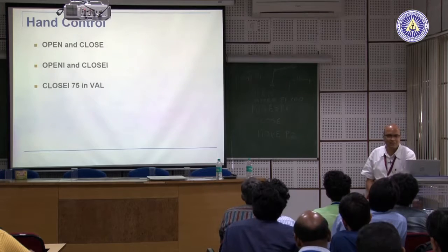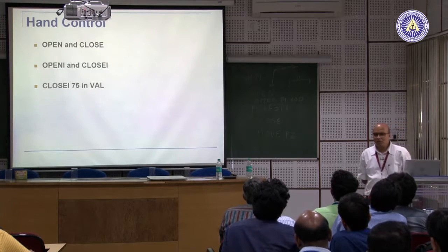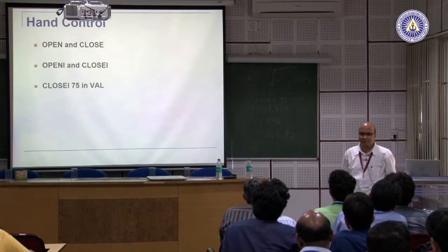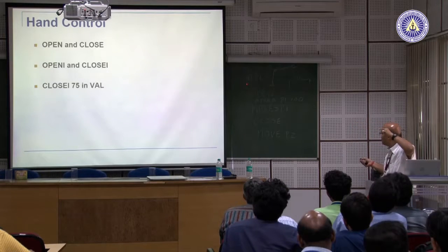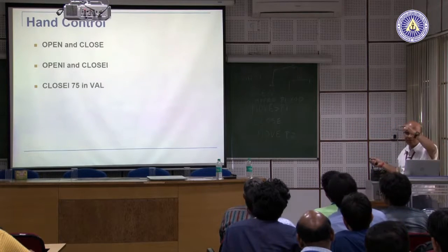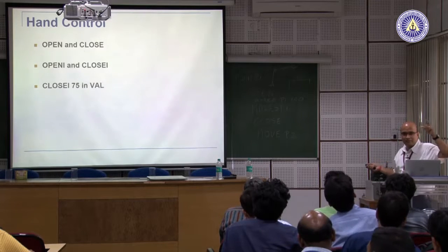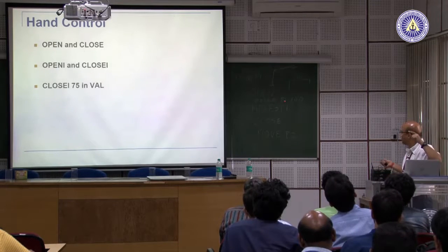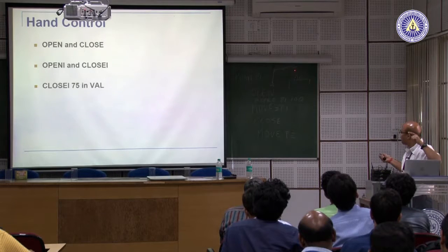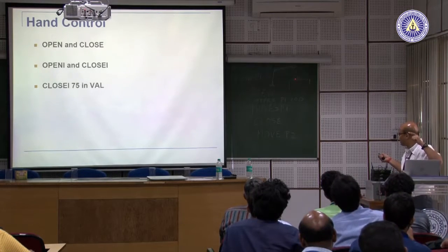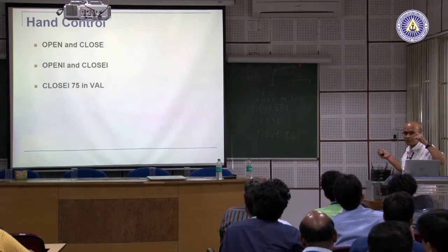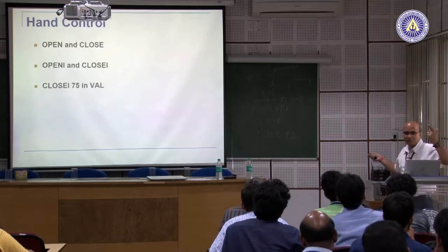So, if you think a little bit about how a program executes, it takes line by line. It starts with the top line. So, it will take the first line, point P1 assigned, value is assigned. Then it will take open, it will start opening. Then it takes approach P1 100, so it is approaching P1 till there. Then it says move P1, so it moves down there, catches it. Then it goes to close, then move P2, it goes to P2, right. That is how a program executes.